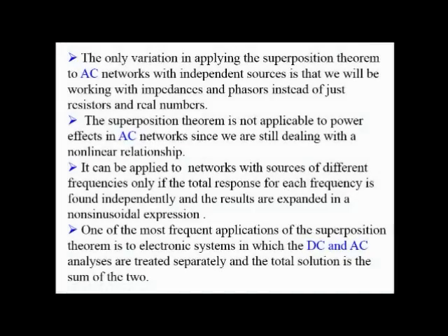Now there are some key points to remember. I think you are getting bored with these points, but then we will proceed to the numericals. The only variation in applying the superposition theorem to AC networks with independent sources is that we'll be working with impedances and phases. The superposition theorem is not applicable to power effects in AC networks. You have to keep in mind that it is not applicable at all to power effects in AC networks, since we are still dealing with a nonlinear relationship.